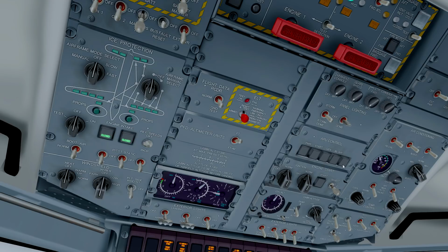So soon the generator will be available, and we will also have bleed air available in order to get some air conditioning running through the cabin. Alright, as you can see, the power is now on. In this case, the APU is not providing electrical power because we still have the external power connected and providing that service.